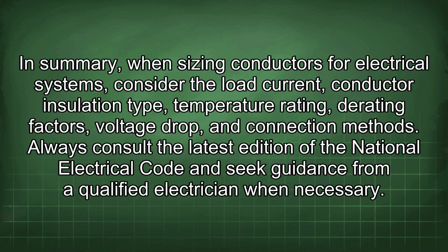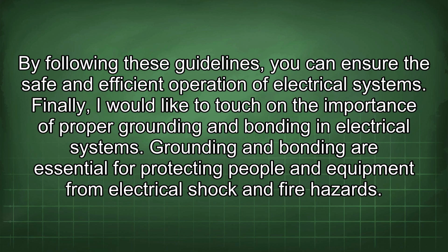In summary, when sizing conductors for electrical systems, consider the load current, conductor insulation type, temperature rating, derating factors, voltage drop, and connection methods. Always consult the latest edition of the National Electrical Code and seek guidance from a qualified electrician when necessary. By following these guidelines, you can ensure the safe and efficient operation of electrical systems.